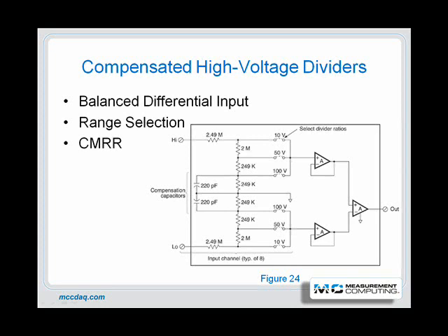It's not uncommon to find that when the AC voltages are calibrated to within 0.01% at the divider network, the voltages reaching the data acquisition system input terminals may be out of tolerance by as much as 5%. This is because the lead capacitance enters into the divider equation.